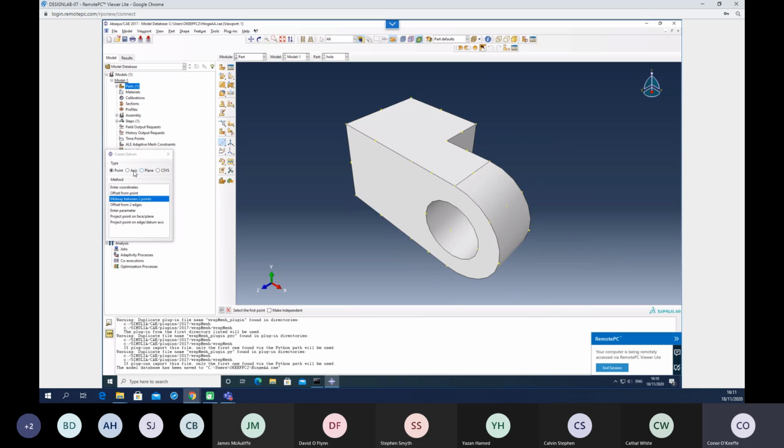So now we want an axis line, 2 points. Okay, and we'll use that axis line and one of these points to create our sketch plane. So we use point and normal, select our point and our normal. There we go. So here's our new sketch plane. In the assignment brief, again, we actually create our sketch down here, and then we upload it. But there's no need to do that. It's just adding to the workload.